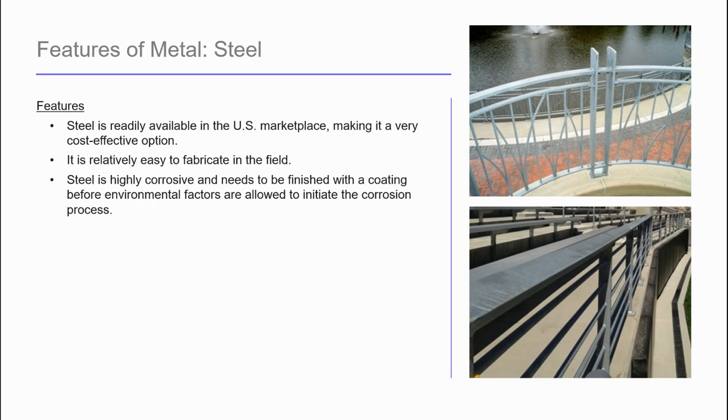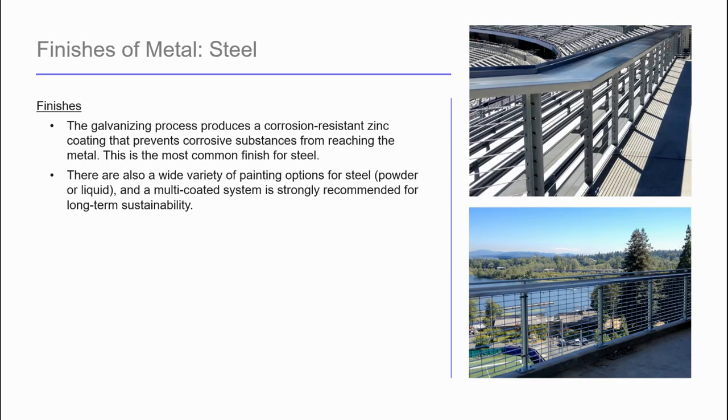The galvanizing is a chemical procedure. That's actually not just a coating, though. It's a chemically bonded zinc layer. So that can be effective if you don't mind the hot dip galvanized sort of industrial look. Of course, you can paint it. There's good coatings out there, but you have to maintain those coatings. And as we talked about, here's the two most common. To go into some detail on those again, the hot dip galvanizing doesn't really need to be maintained per se.